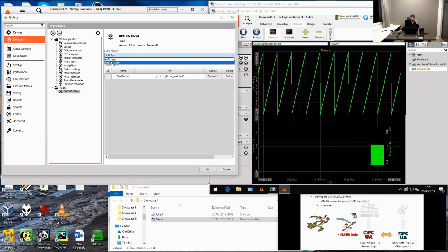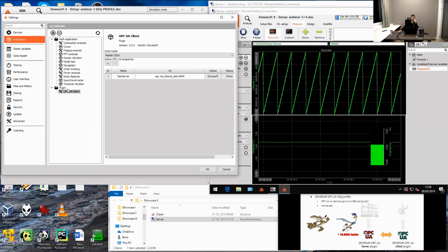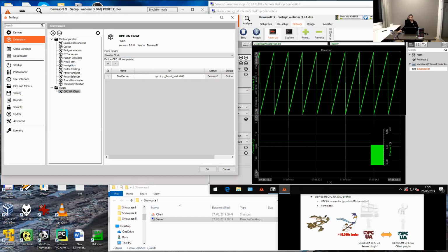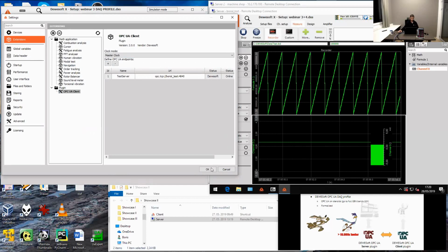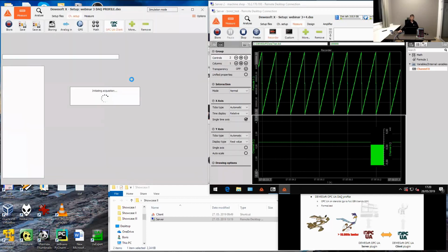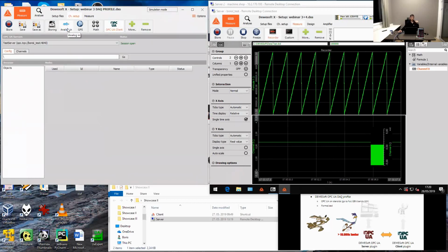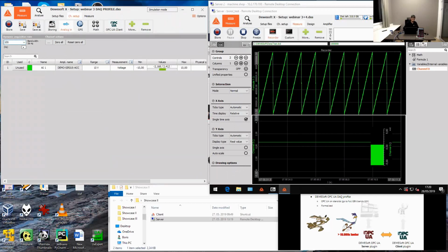So here we check master clock in OPC UA Client settings. The assumption is that the clocks on all nodes are perfectly synchronized. And we also have to check dynamic acquisition rate. It's under analog in. So this also has to be pushed up.